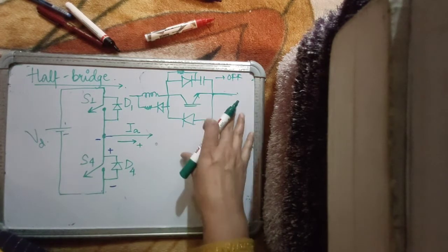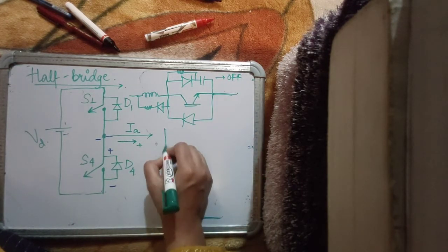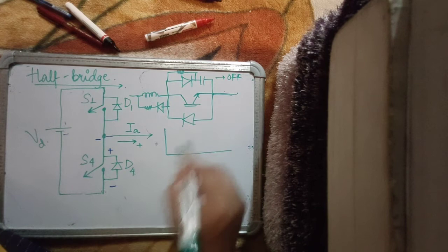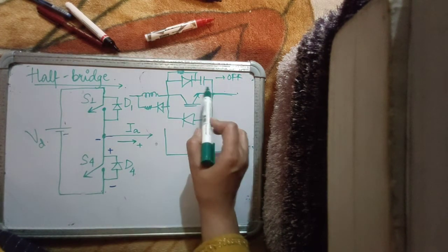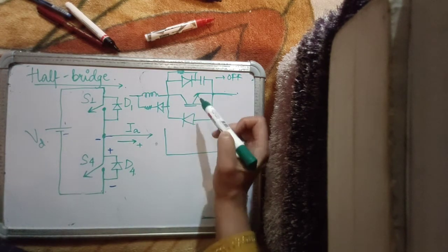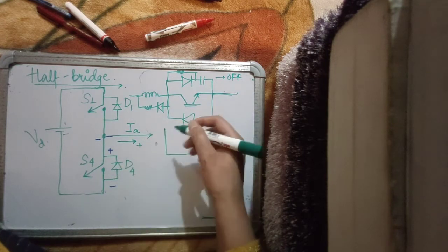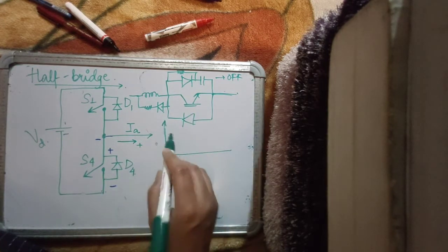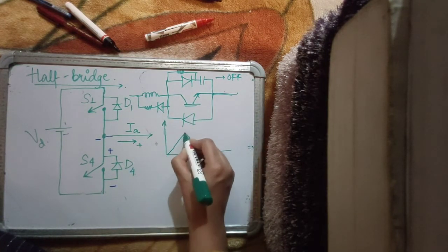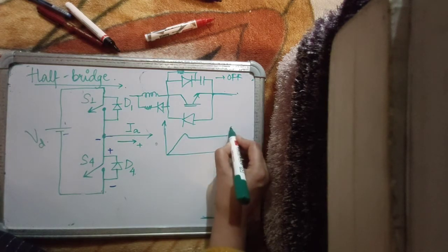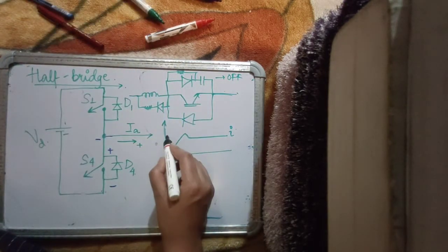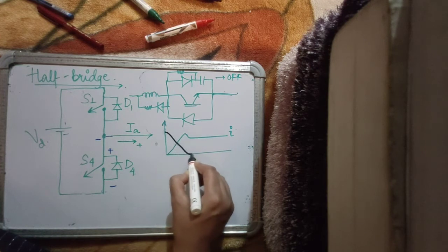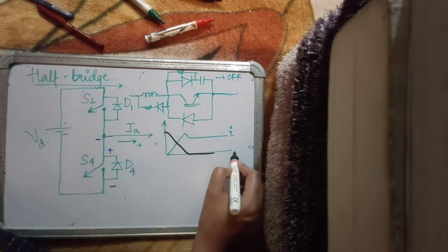If you use this kind of circuit, then you will ensure that because of these snubbers, the device voltages and device currents will show a transition much earlier, which means that when you turn on the device, the current will start rising and the voltage will start falling instantly rather than waiting and then falling.